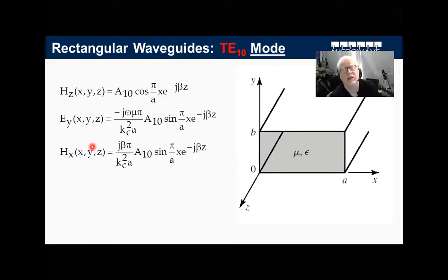I chose the TE mode for 2 reasons actually. The first is that the TE is the most famous mode, the fundamental mode. And the second is that it's somehow easier mathematically because we have only 3 electrical and magnetic field components instead of 6. We have another 3 with zeros. That's why life is somehow easier in dealing with it. That's why I chose the TE10 mode. However, as I mentioned, you can typically apply the same approach on any other mode.